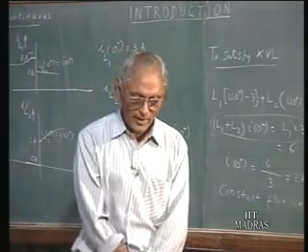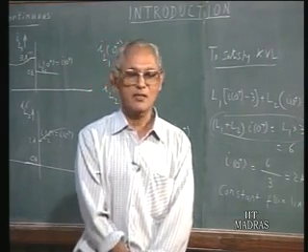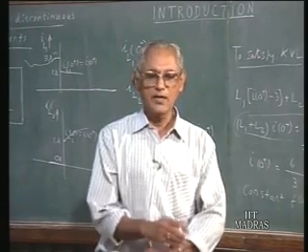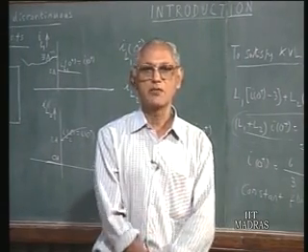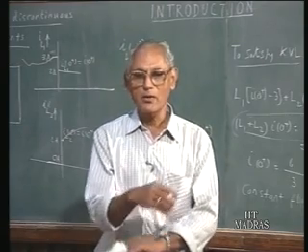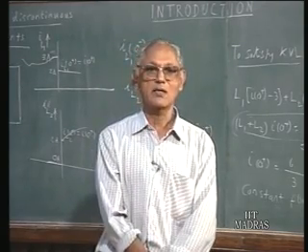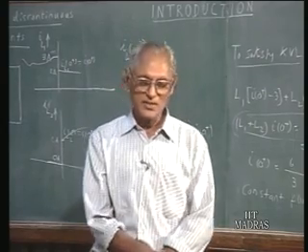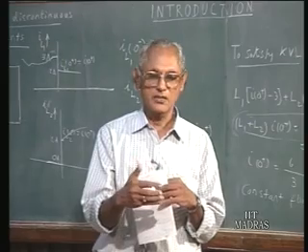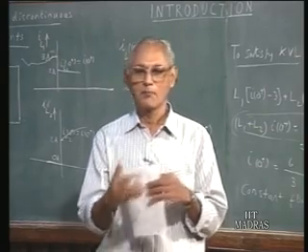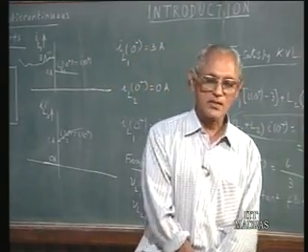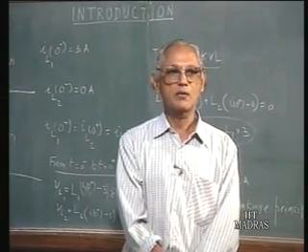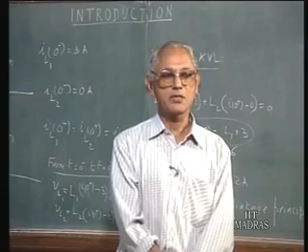Remember that the reason we normally say inductor current is continuous in the elementary treatment is that if the inductor current had jumped, there must be an impulse voltage, an infinite voltage, across the inductor. Since all other voltages are finite, this infinite voltage cannot exist, therefore inductor current must be continuous. But in situations like this, no doubt an impulse voltage arises across an inductor, but that is matched by another impulse voltage across a second inductor or a third inductor, as the case may be, and Kirchhoff's current law can be satisfied only if such impulse voltages exist.